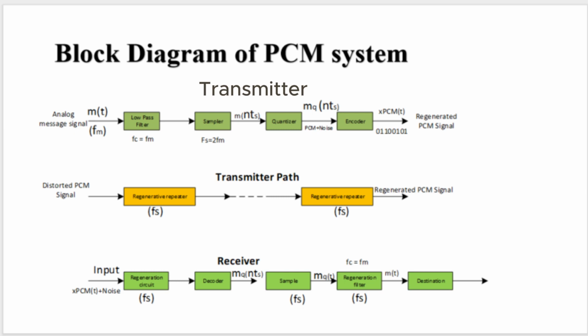So once more, pulse code modulation. The pulse code modulator technique samples the input signal m(t) at the sampling frequency. This sampled variable amplitude pulse is then digitized by the analog to digital converter. The signal is first passed through a sampler which samples at the rate of fs, where the output of the sampler is ms(t).